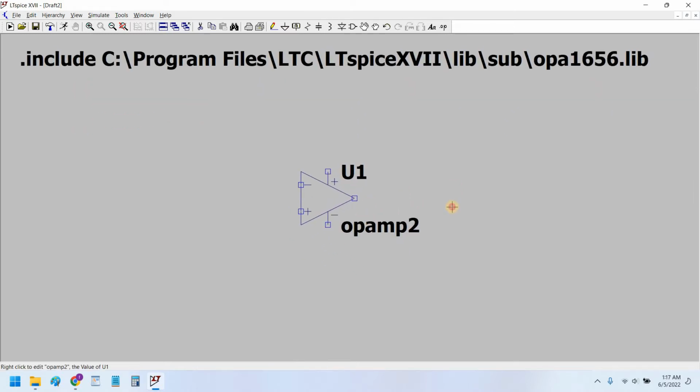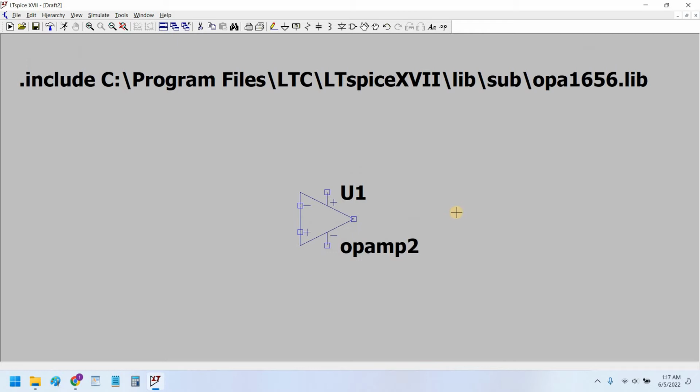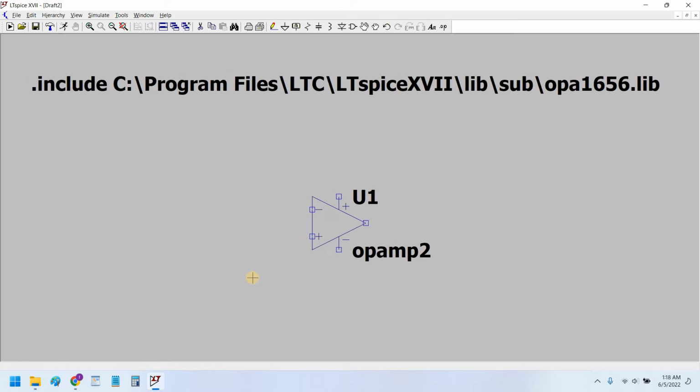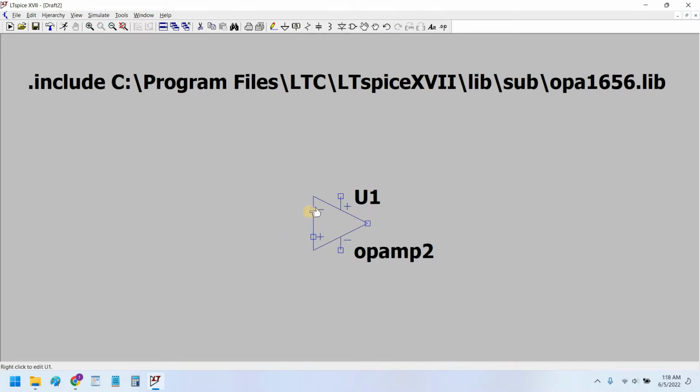A non-inverting amplifier is an amplifier in which the input is given at the positive terminal of the OPAMP. You have to remember this. This is very important. And on the negative pin, we have a feedback resistor to the output.